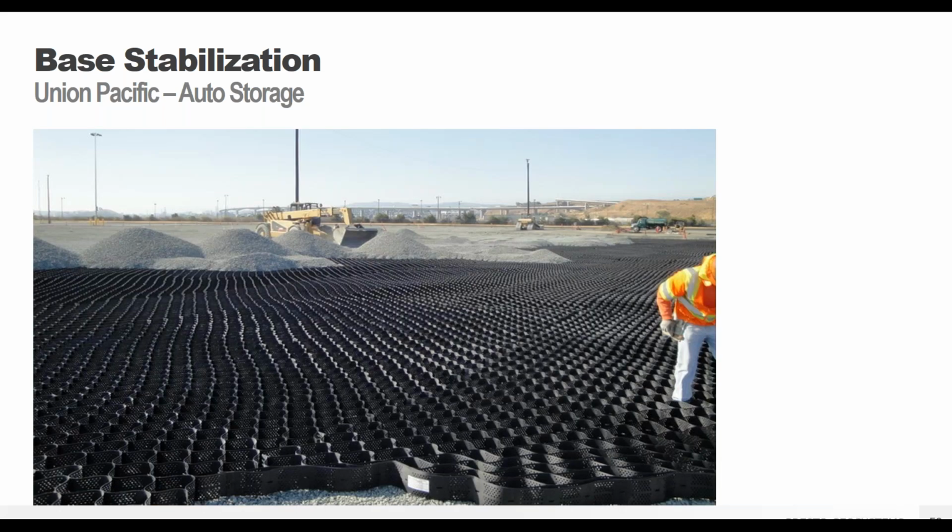So again, a good mid-construction photo, expanding all the GeoWeb panels out and then filling in with stone. And really it becomes a really quick job. Once the contractors have done just a little bit, they see that it's really fast, really easy. And really, placing the panels is almost always faster than infilling them, even if you have equipment moving that stone. So you're not going to have to worry about sequencing or anything like that.